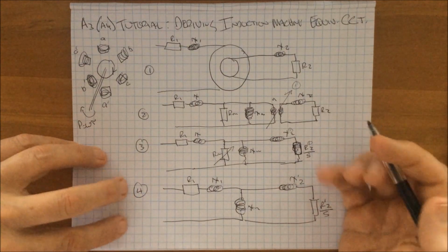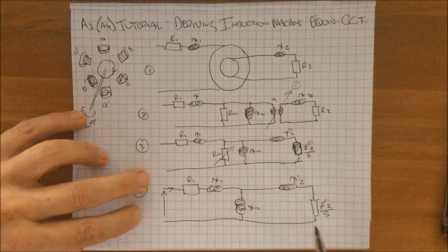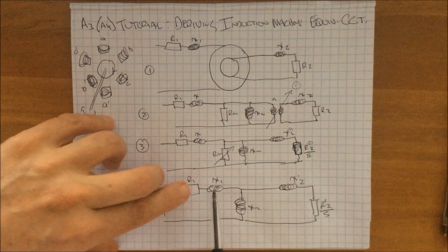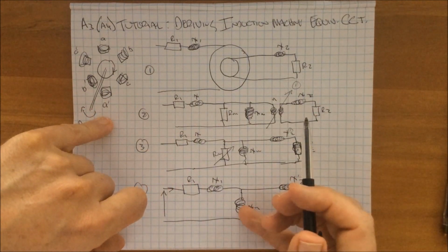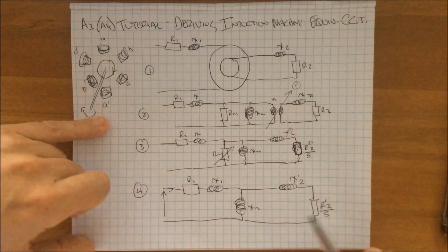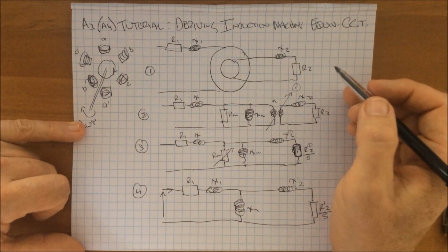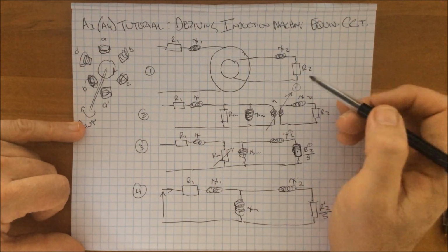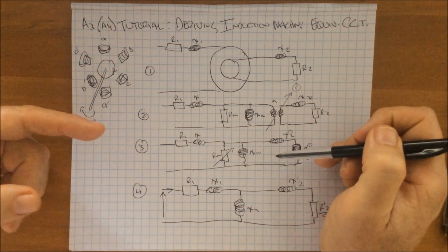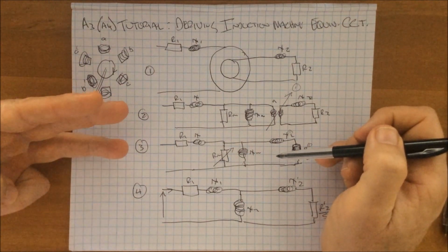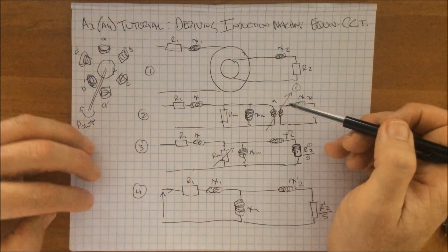You can see here that you could measure the voltage here, the current here. The impedance would obviously be these two here in series with these two in parallel with the magnetizing reactance. So I'll put up another video on how to go through and find these things out by doing a DC test, a locked rotor test, and a no-load test. By doing those tests, we can then find out what these values are.